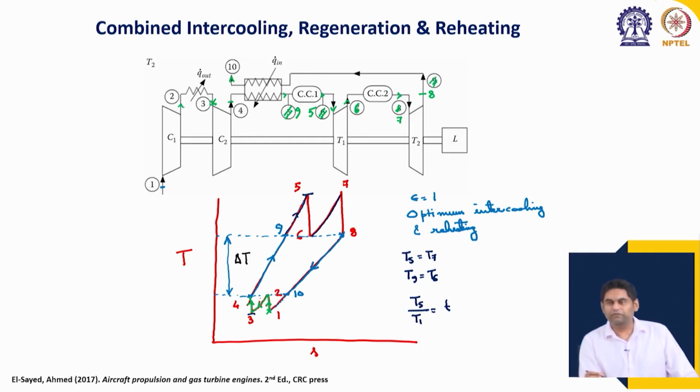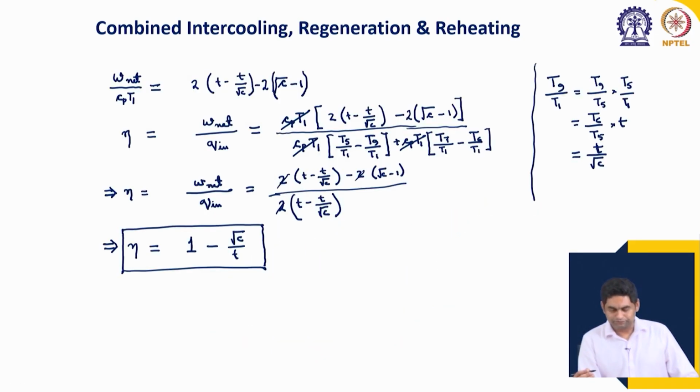So, it becomes bulky, but for industrial gas turbines, for power generation, where mobility is not of concern and it is installed at a fixed location, in those cases we can get very high performance characteristics by using all this together. For other applications where weight is of high importance, like aerospace applications, of course, these modifications are not important. There we will study later, the modifications are closely related to that of the simple Brayton cycle.